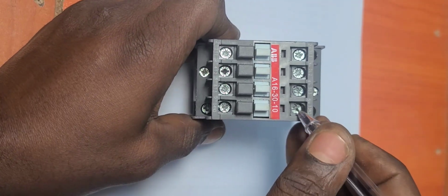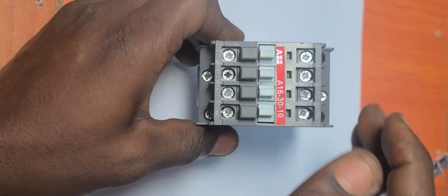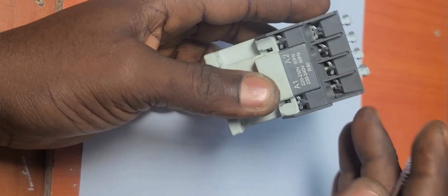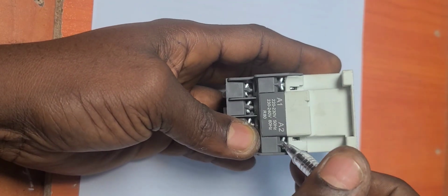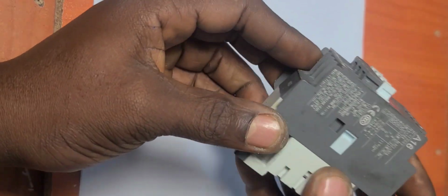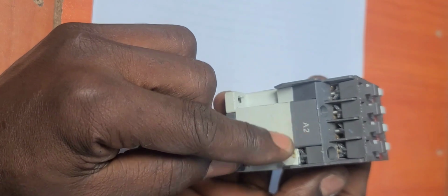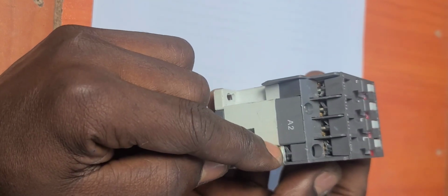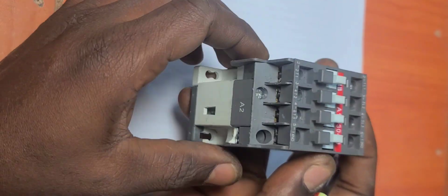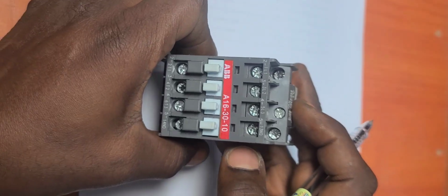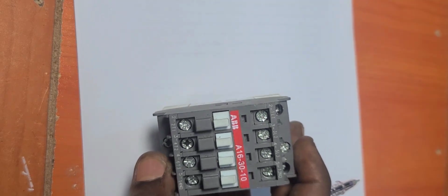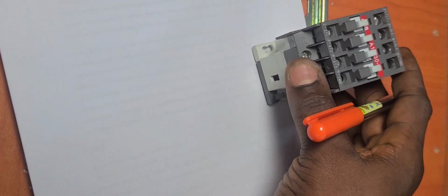All right, and then we also have the auxiliary contacts here. And then of course we have one of the coil contacts A2, and then we have the A1 and also A2. This A2 here is a straight conductor from here all the way to the back where you have this other A2. The A2 you are going to choose is dependent on your cable arrangement and the position of this contactor in the electrical panel. All right, so first of all, before we proceed, let us show what this thing means in a diagram.